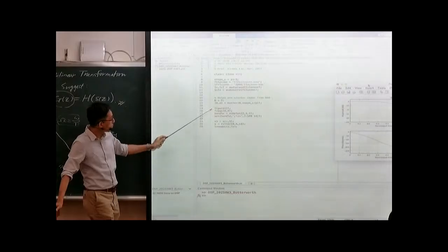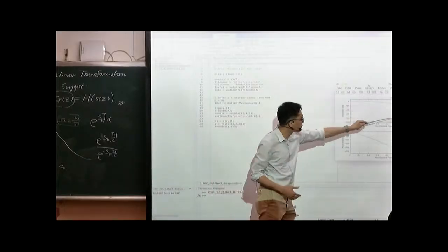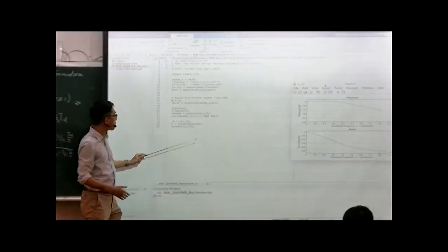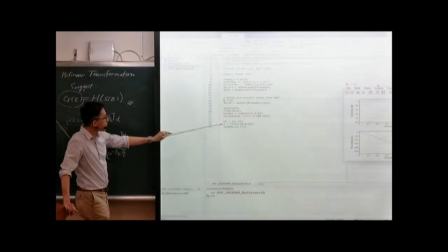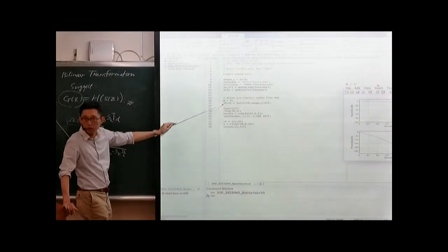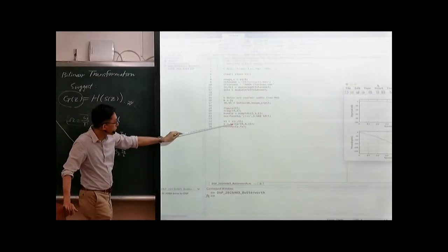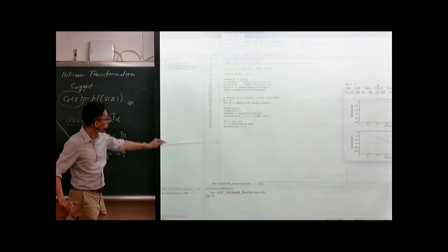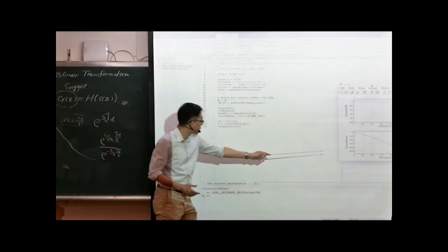And from there, you can use freqz to plot the frequency response, the magnitude response in dB, as well as the phase response. That's a very useful function to know, freqz. And then we can process any input with the filter. Knowing B and A, we can just filter our signal with B of Z divided by A of Z. So that's simple. No more than 25 lines of MATLAB. Already we can plot the frequency response and we can filter the signal.